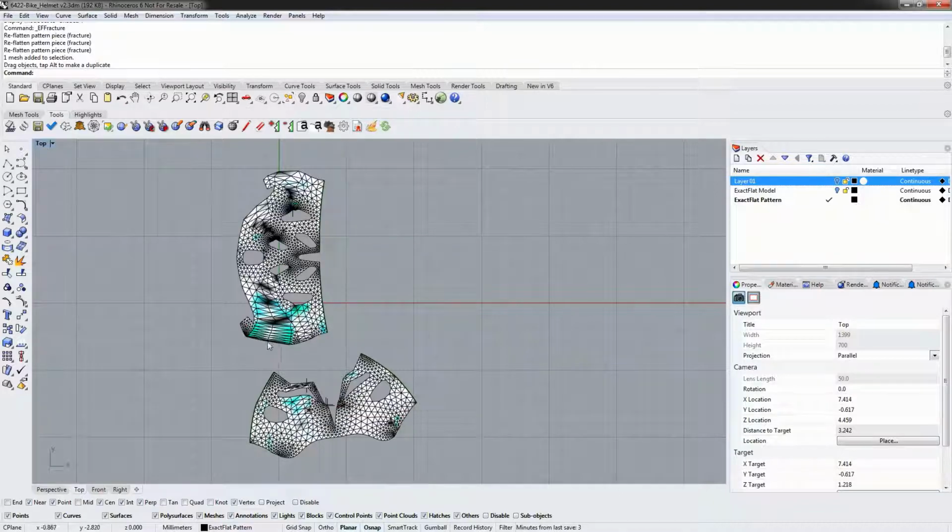By contrast, the optimizer is not fast at all, but it considers the whole model in relation to the pattern, and it's going to reduce the average energy density of the pattern to produce a production ready final flat pattern. It also does this using the mechanical properties of the selected material, whereas the pre-flatteners do not use material properties.